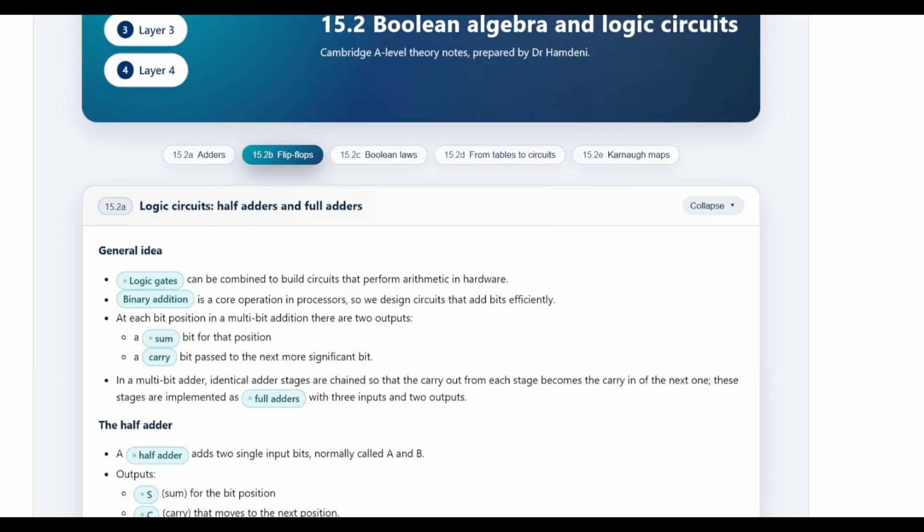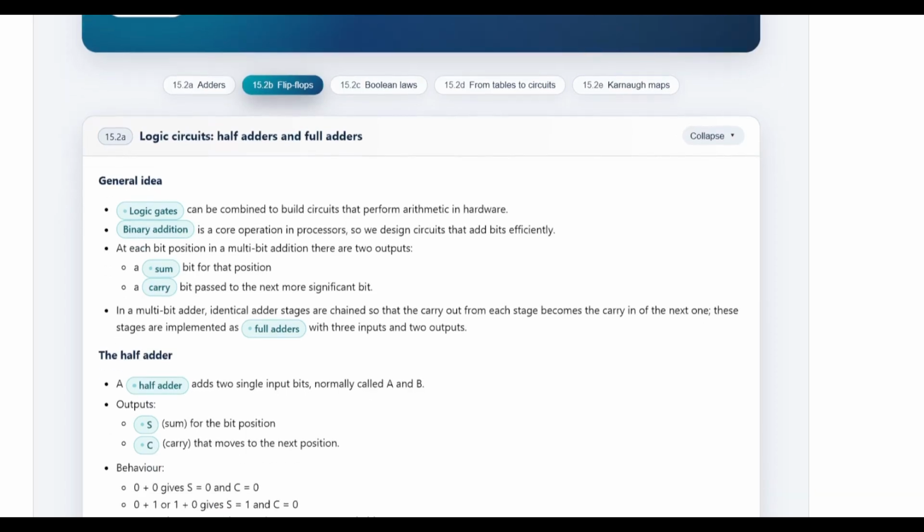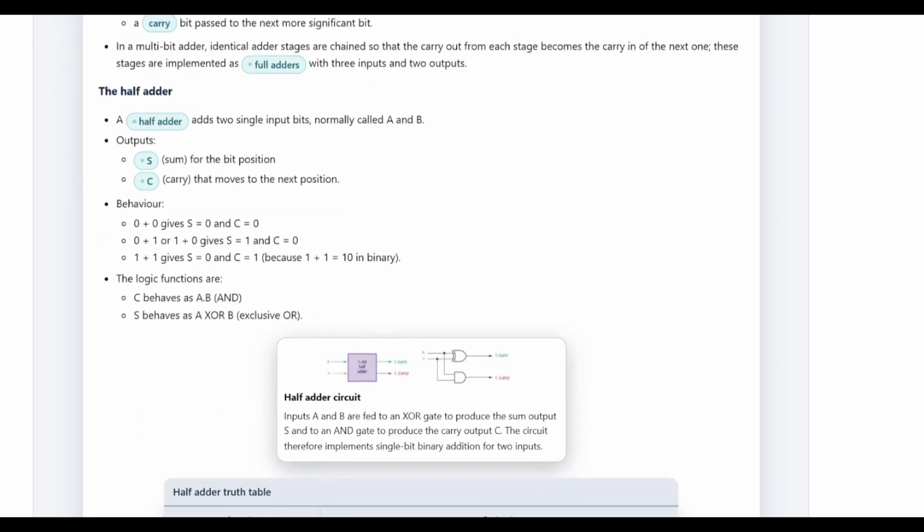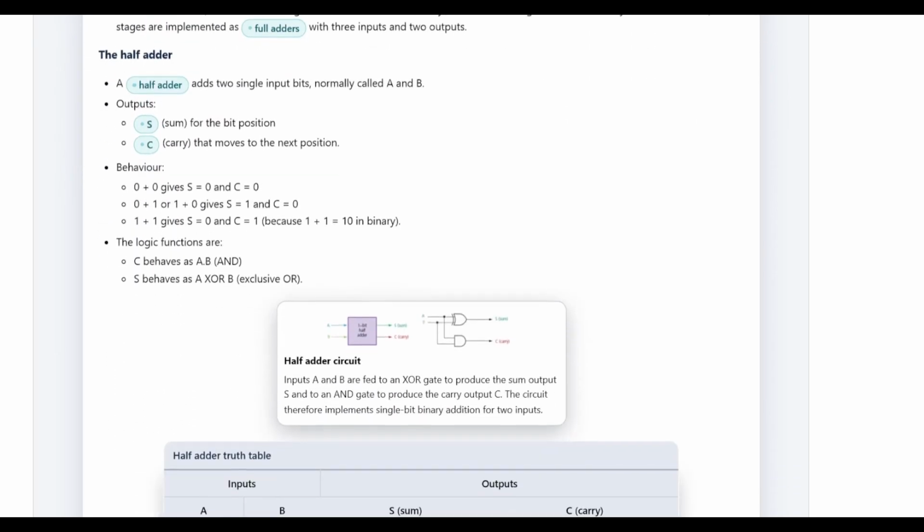We talked yesterday about the half adder and the full adder. And we said that the half adder is the one that does the addition of two binary digits, like 0 plus 0. When we add two binary 0 plus 0, it will give us 0. This will be saved in S.